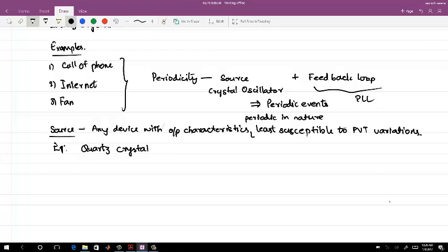And if this quartz crystal is carved out in a fork kind of shape, you cut it out from the crystal, and it can move depending on how you apply the electric field. So this quartz crystal works on the phenomenon of inverse piezoelectricity. It's also called piezoelectricity.